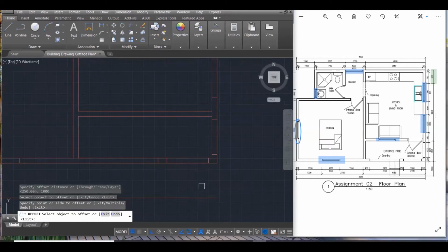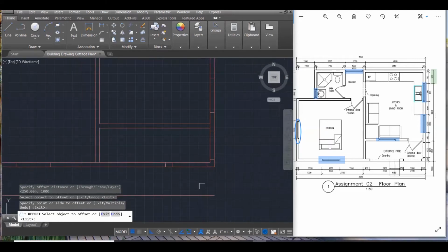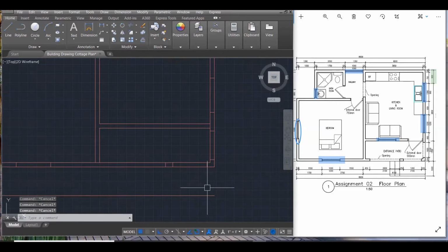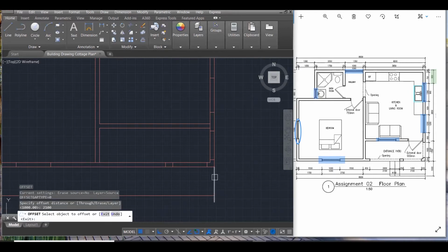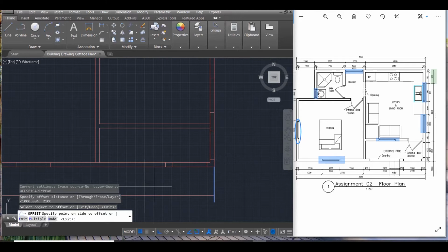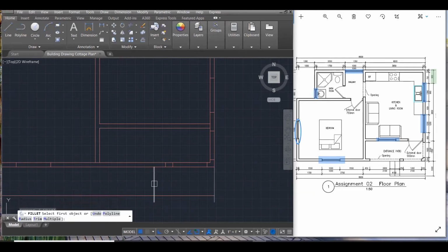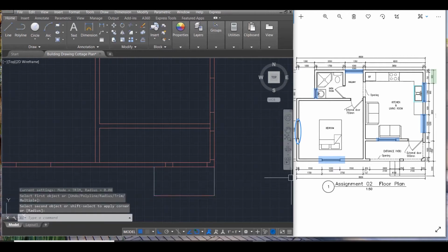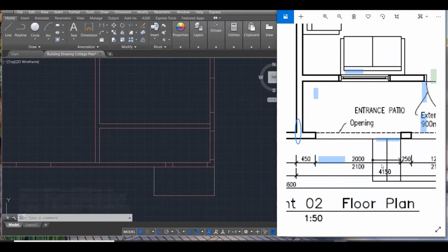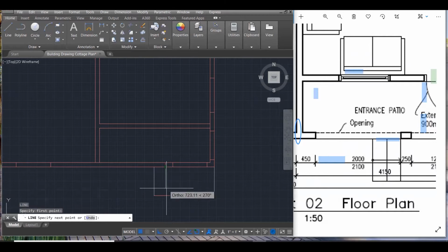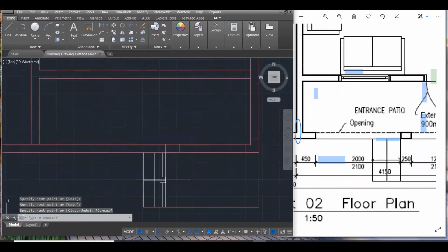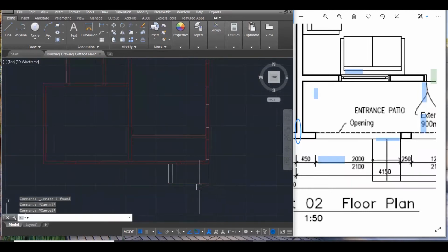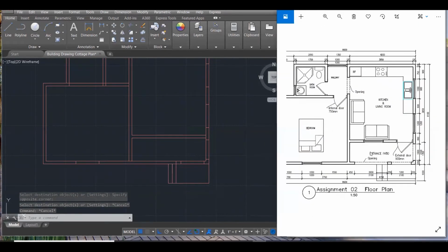1000. And this is a bit tricky around here. How do we actually get in this full thing? Tempted to say the full thing is 21. Let's see the alpha line and pull down a line here. Offset 2100, enter. Yep, 2100 is there, and then we put in our two steps in between here. To get these two steps in, I'm just going to draw down a line from here and then divide the space in two, and that gives me my two steps. Yeah, just like that. The reason I did that is I didn't see any information to indicate what those steps would be. All right.